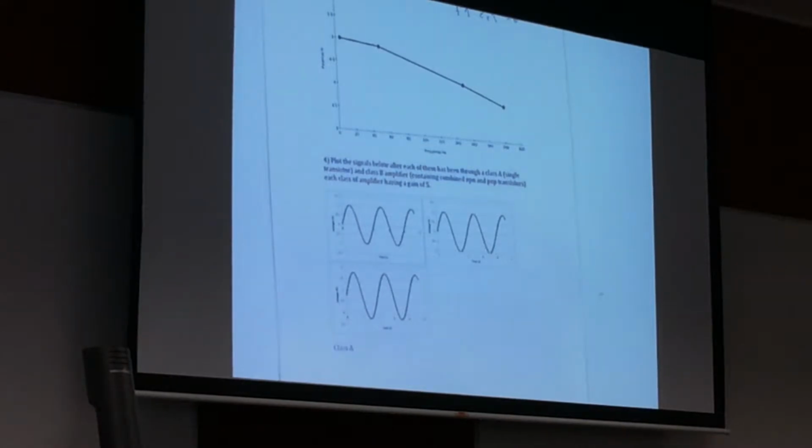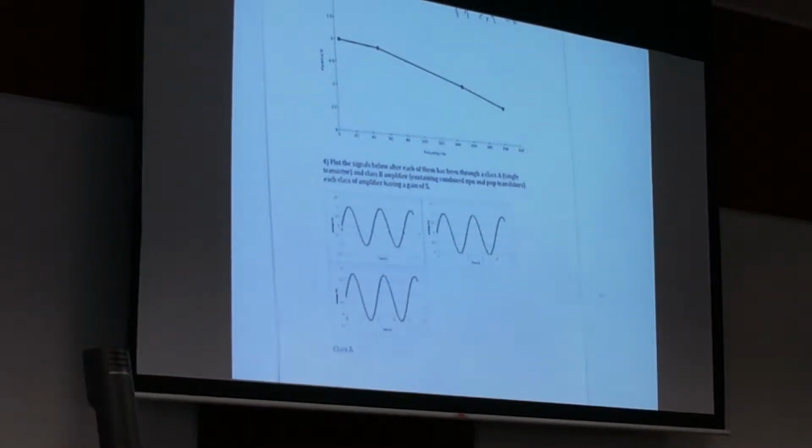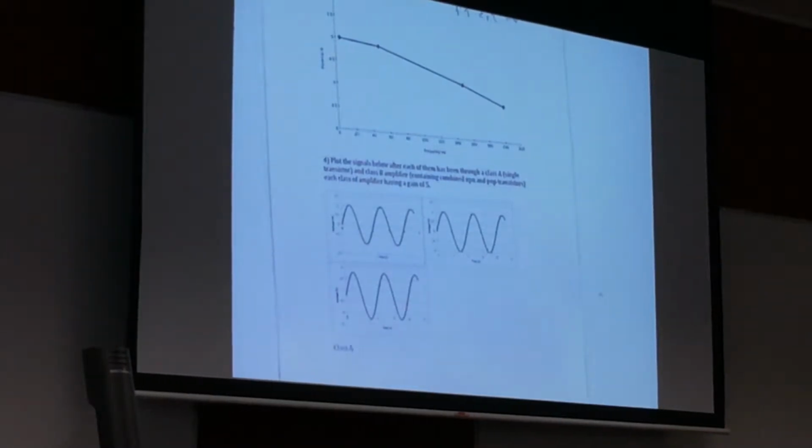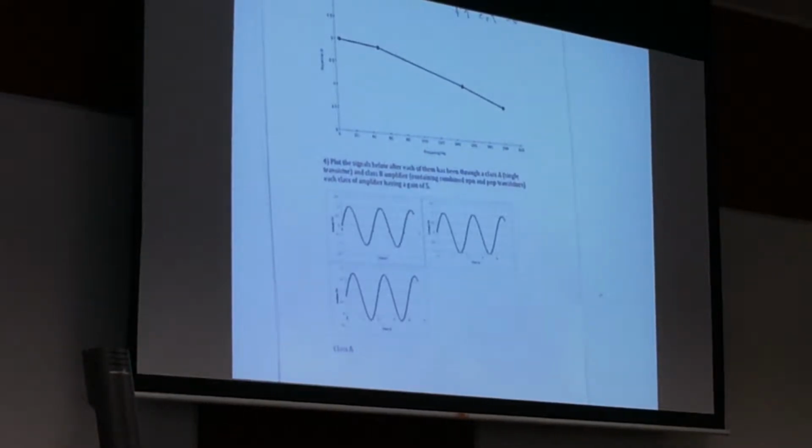And for a diode to conduct, you need at least to provide some amount of voltage to overcome the barrier. And that is about 0.6 volts. So even though it is only operating half cycle, for example at a positive cycle, you need to have at least 0.6 before the whole device can turn on. So in other words, the whole system will click, instead of at 0 volts, it will click at 0.6 volts.